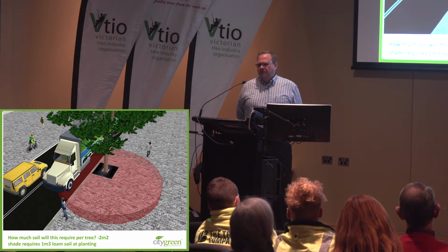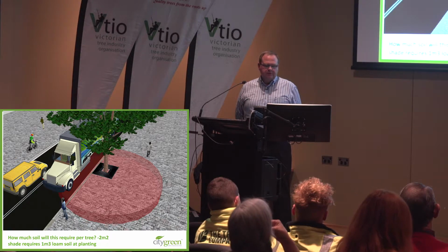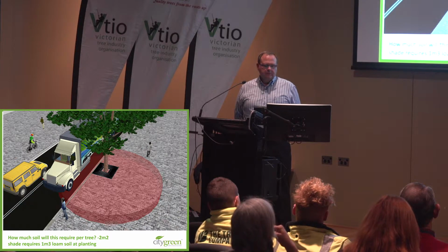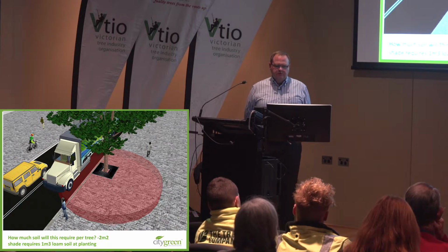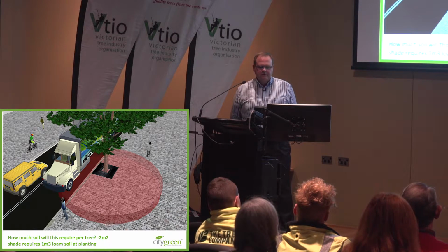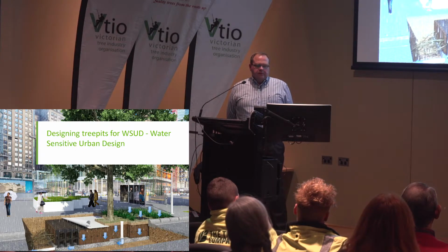It ties in very, very closely to what's known as the Crown projection formula, which is 0.6 of a metre in depth times the area of the mature tree canopy. So it's virtually identical. These are all rules of thumb. There's much more complex formulae out there, as we know, that take into consideration regional evapotranspiration rates, etc. But this is a good rule of thumb. So that's for shading.